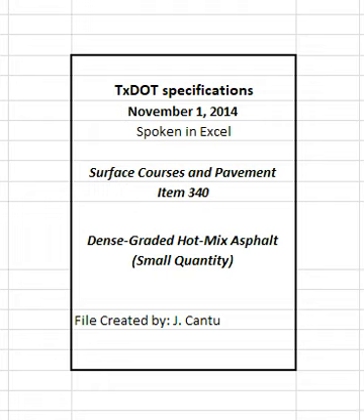The specified layer thickness is based on the rate of 110 pounds/square yard for each inch of pavement unless another rate is shown on the plans. Compact miscellaneous areas in accordance with Section 340.4.7, Compaction. Miscellaneous areas are not subject to in-place air void determination except for temporary detours when shown on the plans.